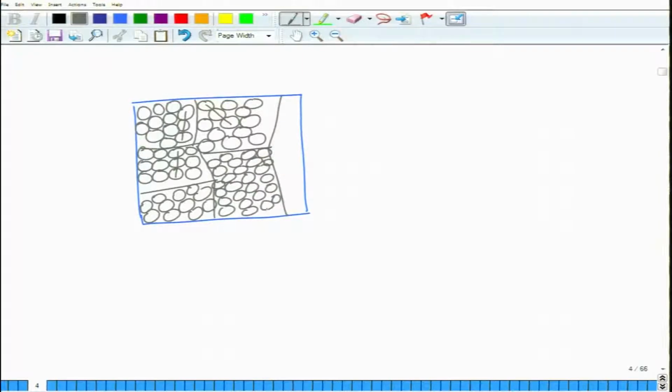If I take only the close packed direction, in this case it happens to be here, in this case here, in this case here, and in this case here. So it is all over the place, right. The same HKL direction has different orientation in different places, and these regions of different crystal orientation are called grains, and the boundaries between them are called grain boundaries.